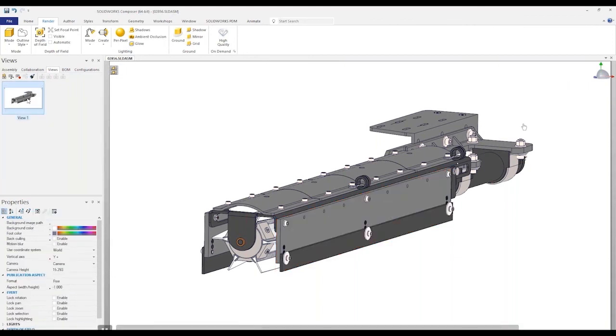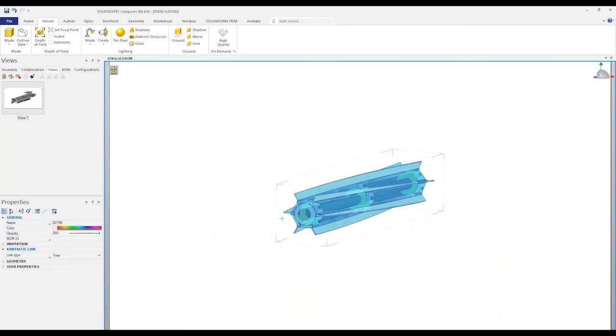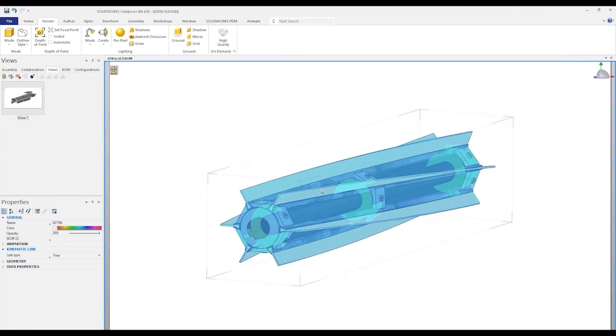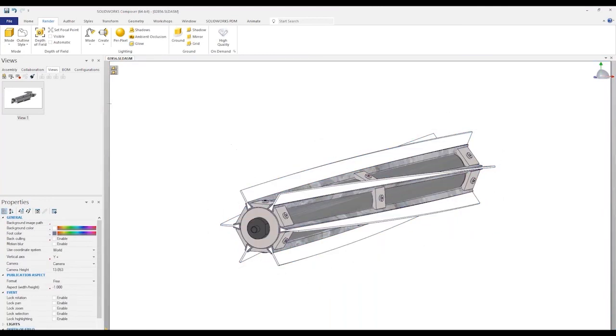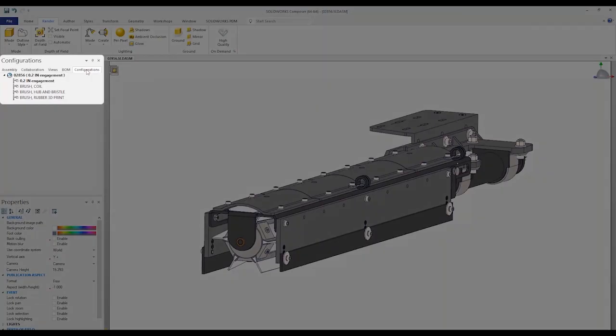So the next step for this replacement part catalog of the subassembly is creating some views for each different head cleaner option. Again, we're leveraging the different subassembly configurations of that. And with a very quick selection here, you can choose to hide all of the unselected components, leaving just the desired cleaning head subassembly.